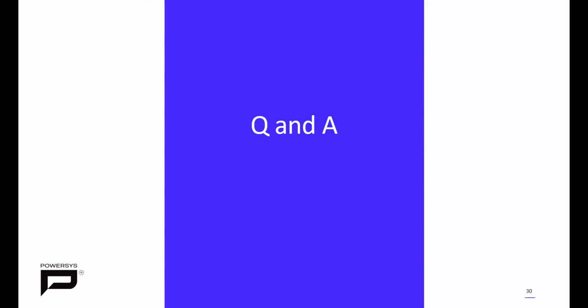And just to add to that, Ryoko, yes, and that's a very good reason to do this kind of co-simulation. That is exactly one of the reasons why we should do this. And you will see some surprises where, if you don't do this kind of simulation, you'll see, oh, I should have been doing this coupled motor and inverter simulation to correctly predict the losses.